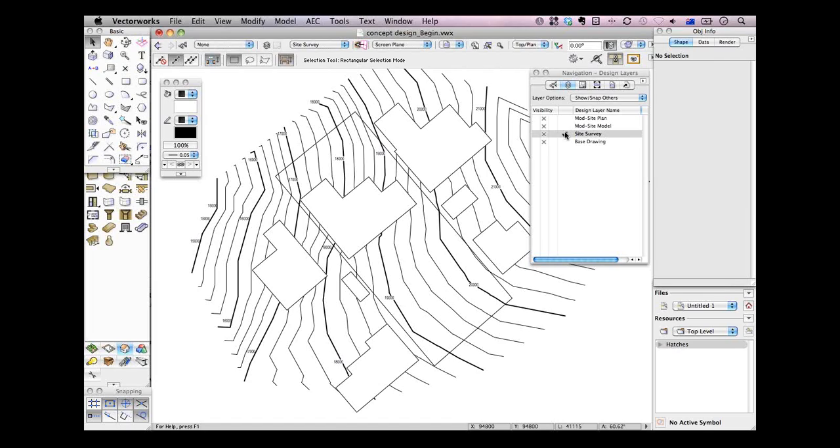So that's something to consider: not to use the Google Earth image, but to actually go and get it surveyed. I know it costs more money, and you have to know whether the client's willing to do that. If they just want a very quick sketch, Google Earth, great. No cost, but be careful of the errors. Site survey, much better quality, much more accurate, but of course you're going to have to pay a surveyor to do it for you.